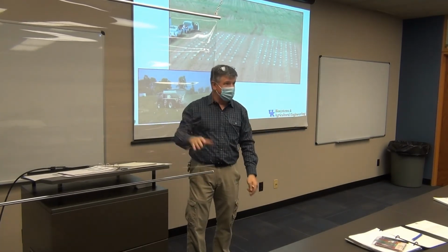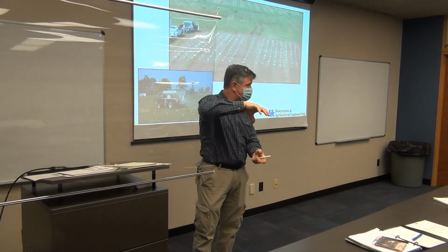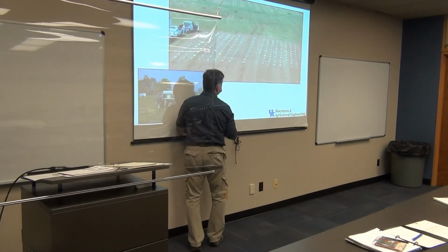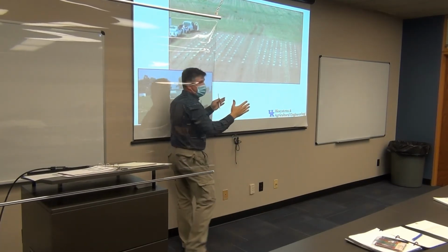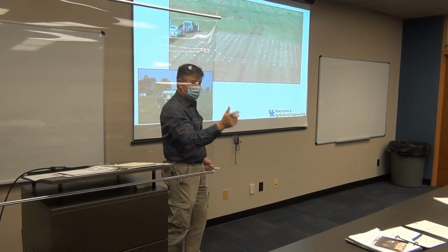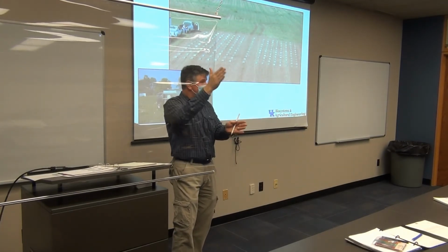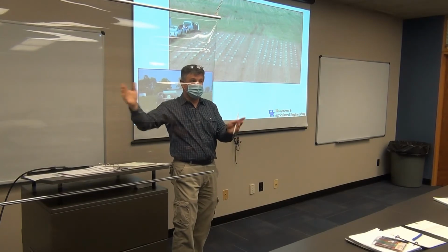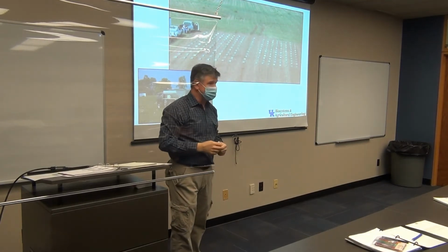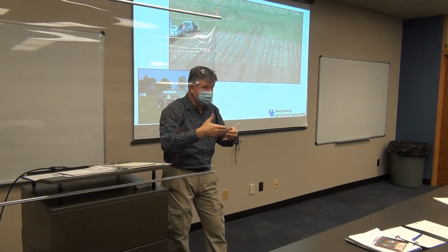Then we lay them on the ground, we drive through there, we spread the stuff, and we let stuff fall in the pans. You pick them up, pour the stuff out, and weigh how much is in each. So I have some discrete values across the width of the machine of how much is spread. Then I can tell you, when you're using this machine, your spread pattern looks like this, so your spacing between every pass across the field should be 50 feet or 60 feet or 48 and a half, or whatever I tell them it needs to be. Okay? So that's what we come up with there. Does that make sense of what we're trying to do?